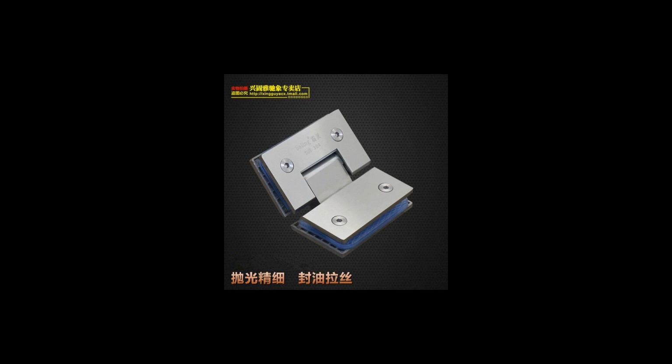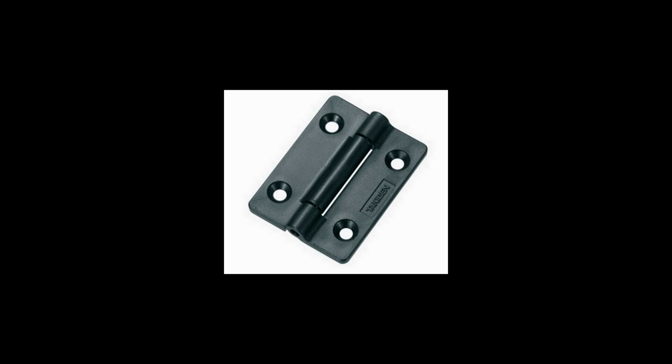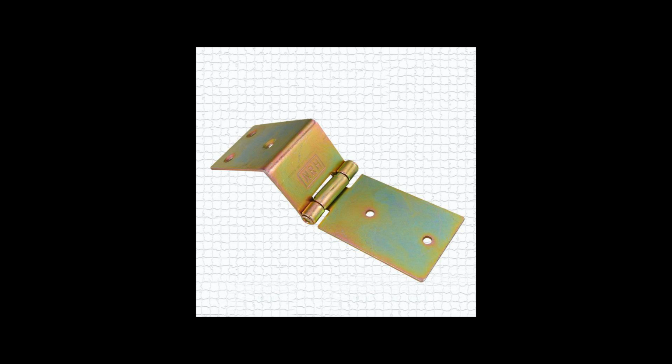Characteristics. End play. Axial movement between the leaves along the axis of the pin. This motion allows the leaves to rotate without binding and is determined by the typical distance between knuckles. Knuckle gap. When both edges of the leaves are aligned. Gauge. Thickness of the leaves. Hinge width. Length from the outer edge of one leaf to the outer edge of the other leaf, perpendicularly across the pin, also known as open width.